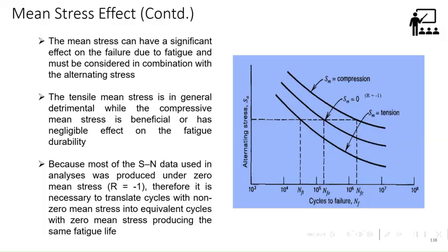Even though you have an SN curve available from experimental data, unfortunately it may not be available for different R or different KT.